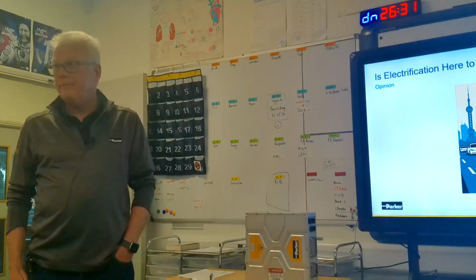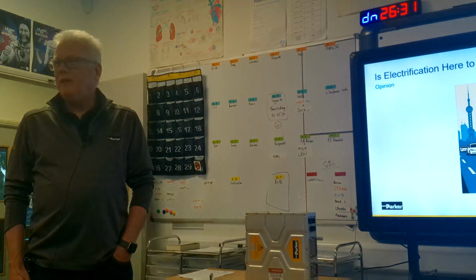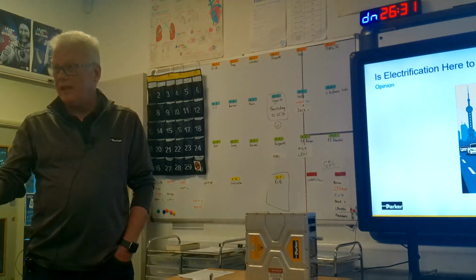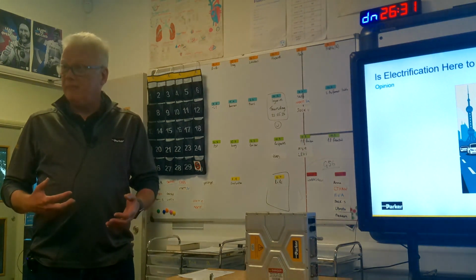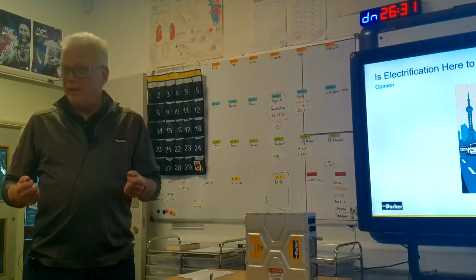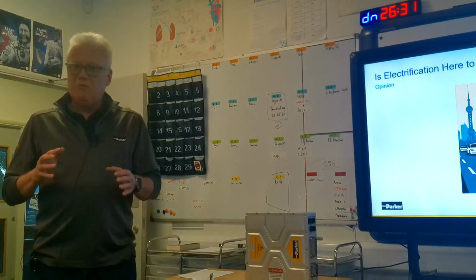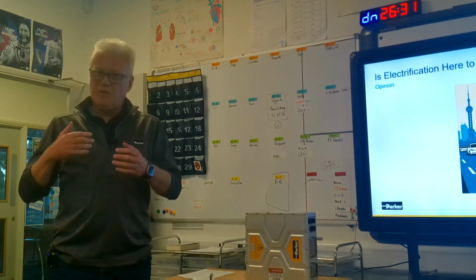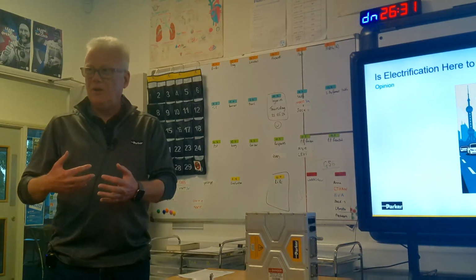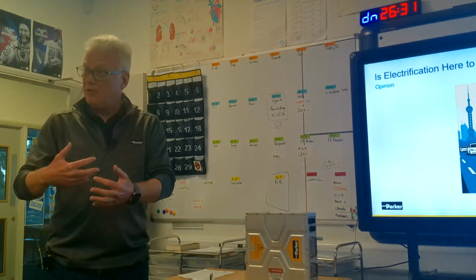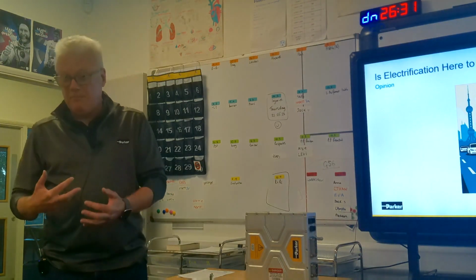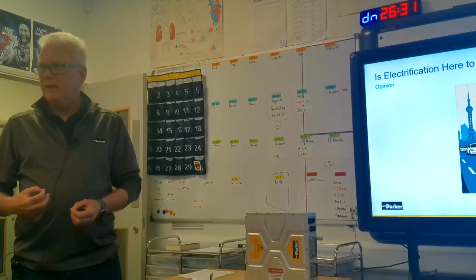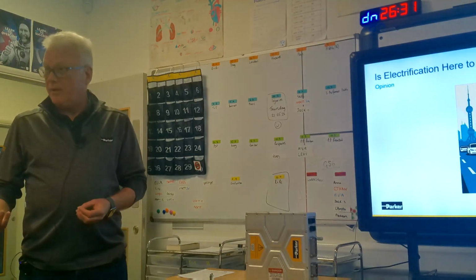Okay. But as far as the failure modes are concerned, I don't want to lose my brakes in the car. You're never going to get rid of having real physical brakes, because of exactly what you've just said. If there was some failure and you didn't have mechanical brakes, you've lost your braking, that's bad. What you would probably see is if you put your brakes on, your first port of call would be braking from the motor, charging the battery up. Then if you really had to and you put your foot on the brake, the mechanical brakes come in. But brake wear as a consequence of that on electric vehicles is pretty light.